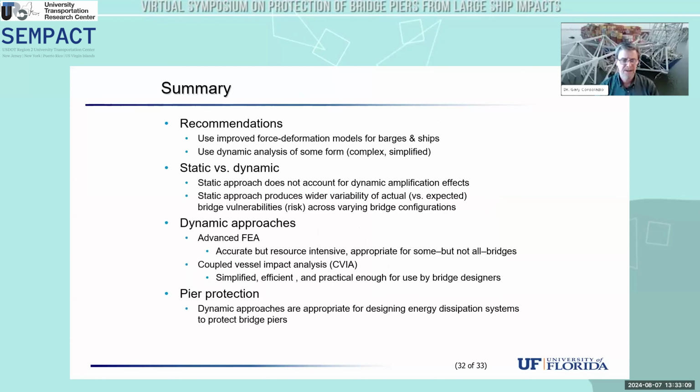All right, so to summarize, my recommendations are to use improved force deformation models for barges and ships. So we've talked about how we've done this for barges. I know some of the other presentations have talked about this similarly for ships. And then to use those simplified representations in some sort of a dynamic analysis. So that can be an LS-DYNA simulation, which is warranted for some cases, or a simplified analysis technique like the coupled vessel impact analysis procedure.